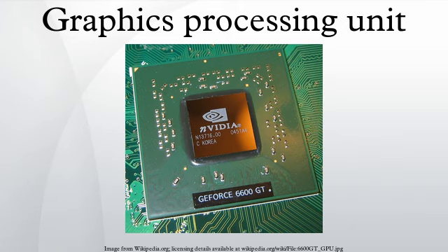Integrated graphics solutions. Integrated graphics solutions, shared graphics solutions, or integrated graphics processors utilize a portion of a computer's system RAM rather than dedicated graphics memory. IGPs can be integrated onto the motherboard as part of the chipset, or within the same die as the CPU. Some of AMD's IGPs use dedicated sideport memory on certain motherboards. Computers with integrated graphics account for 90% of all PC shipments. These solutions are less costly to implement than dedicated graphics solutions, but tend to be less capable.